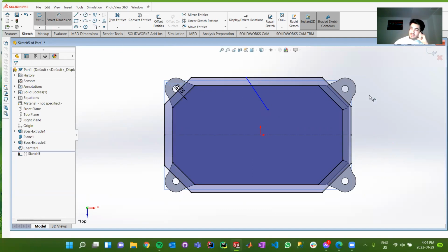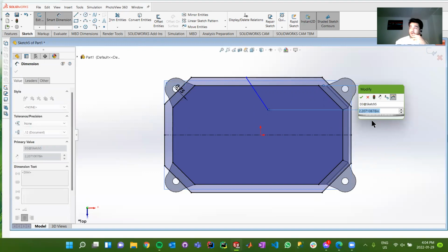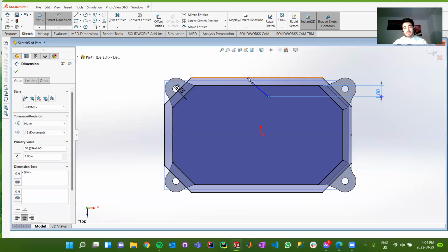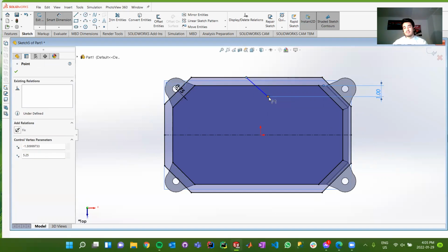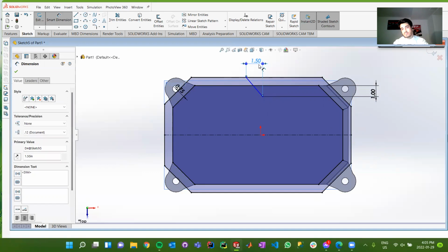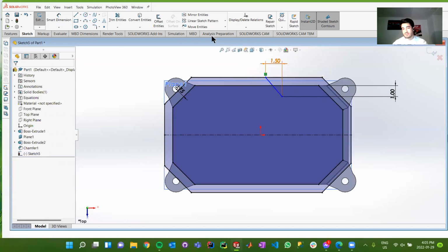And then from there, I'm going to say the endpoint of this particular line that we just drew is about an inch off from the top edge of our assembly. So we'll do that, press OK. And then we'll say that the base of this line, so the horizontal distance from this point to this point, is 1.5 inches apart. And then we can actually translate this about different parts of our sketch as well, which is pretty cool. But we want it to stay perfectly still.